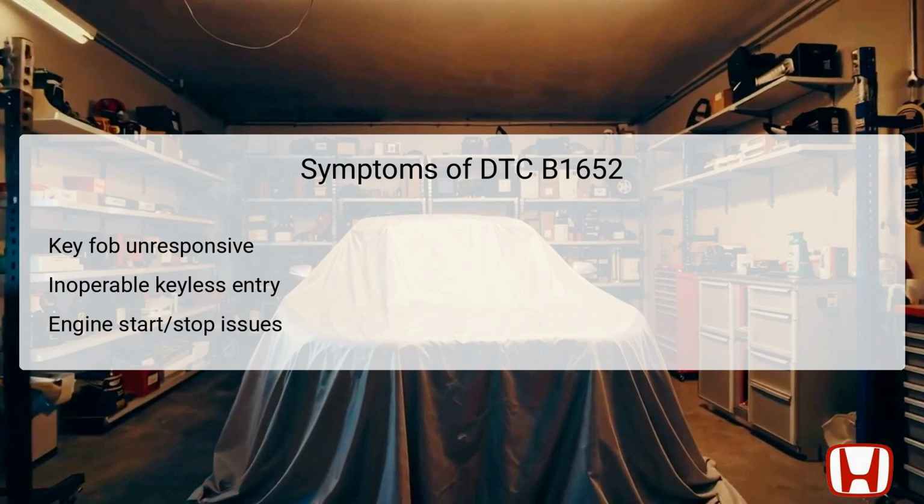An indication of the issue might also be related to the engine's start-stop functionality. If the keyless entry system is compromised, the engine may not start as it should. Users may experience intermittent operability, where sometimes the key fob works and sometimes it does not, hinting at underlying wiring or connection issues. Paying attention to these symptoms will help in diagnosing the DTC accurately.